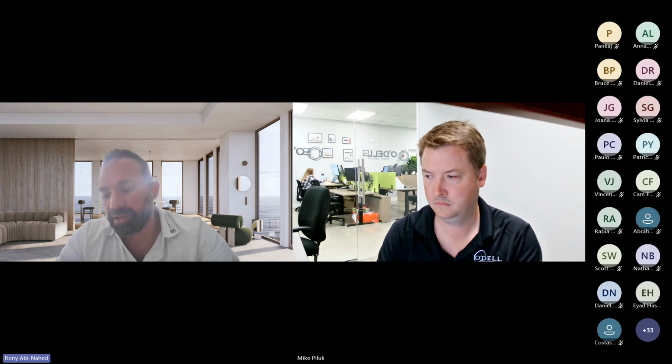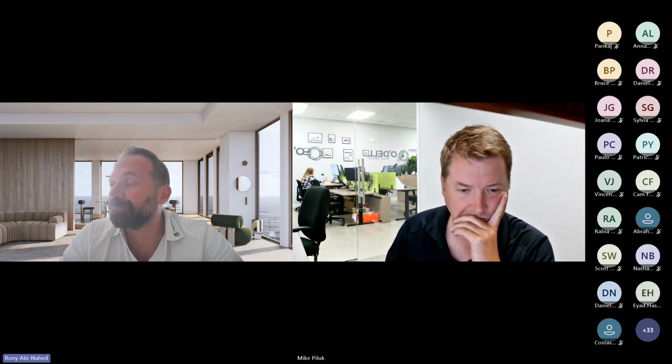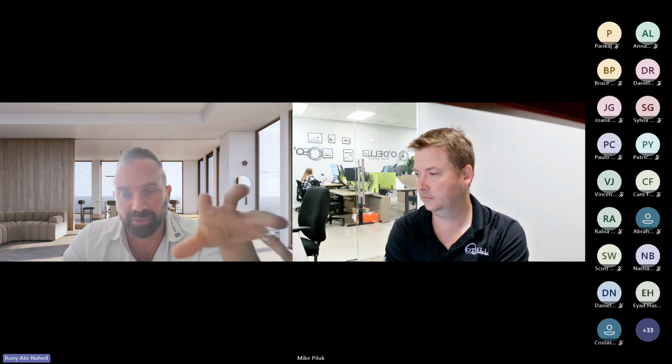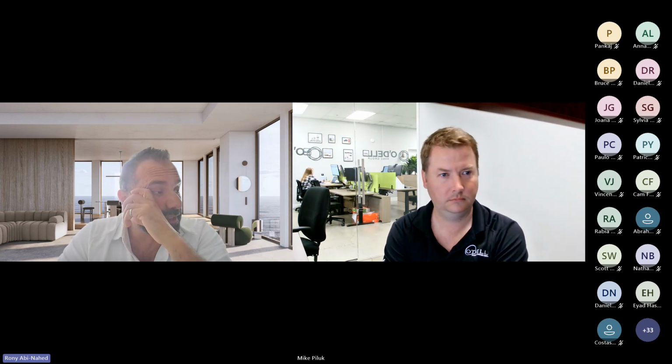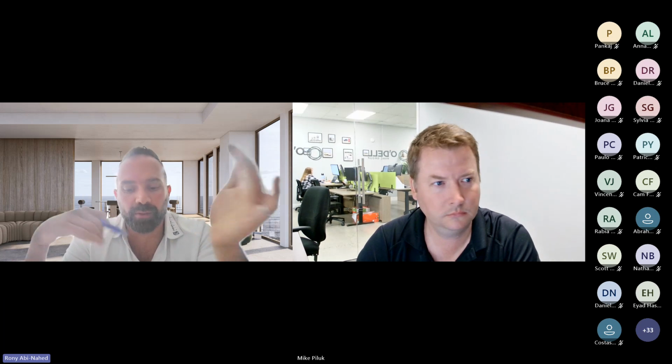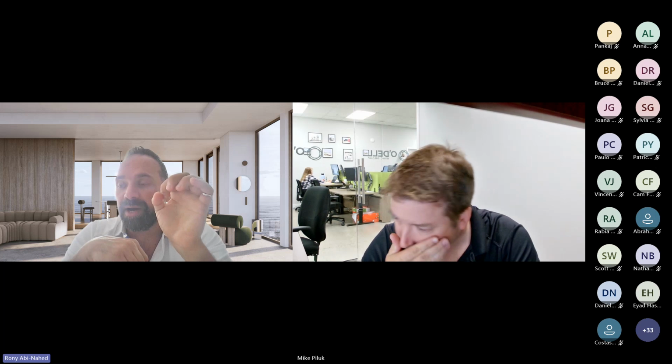What I normally recommend is, I don't know if you're speccing with us or someone else, but whoever you're speccing with, send them a quick draft of your horizontal run, your vertical run, and how it really looks, and then usually we can do the math internally and make sure that you're fine. But in this case, depending on your run, how much vertical, how much horizontal, how many elbows you have, I would recommend upsizing the copper piping a little bit and upsizing your unit.